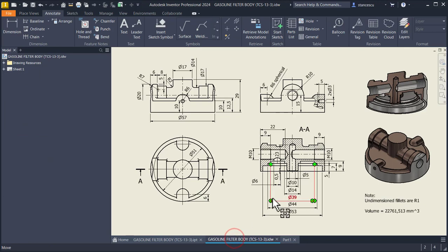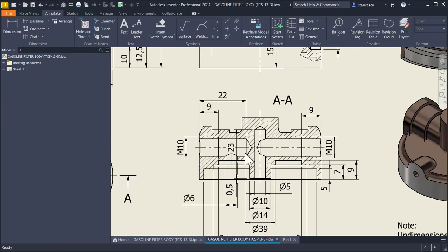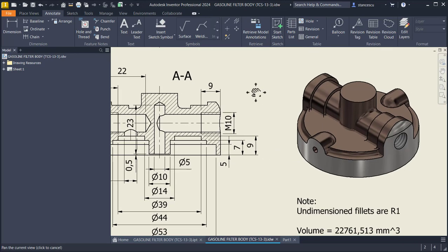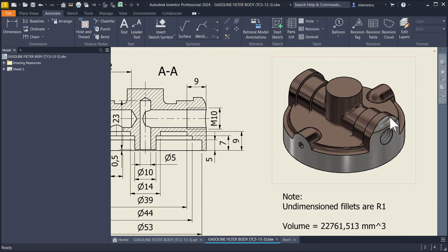Okay, then we have to apply these 2 holes with their dimensions metric 10, 9, 9. This ends at 25 from the face and the other ends to the midplane, this midplane. Okay, the start is from the center of this contour.